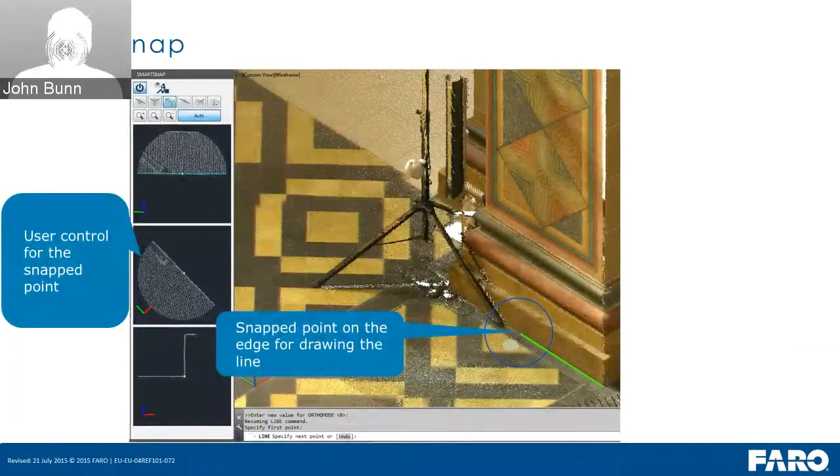If you can kind of see here on the left side, we have a preview that we generate as you click the point. You have an auto mode that you can turn on or off, but if you leave it on, it will actually plot the point for you and give you a confirmation on the left. Now, what you're seeing on the left there is actually 3 different vantage points or viewpoints of that specific point. It's kind of hard to see here, but there's a green dot in the middle of each one of these previews, and that is telling you where that point is. So it allows the user to verify that, yes, it's on an edge from a plan view and from an elevation view, and you can tell that the software found the correct point for you.